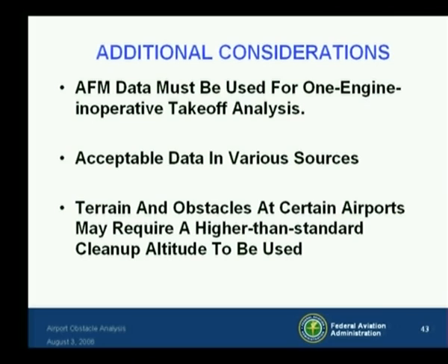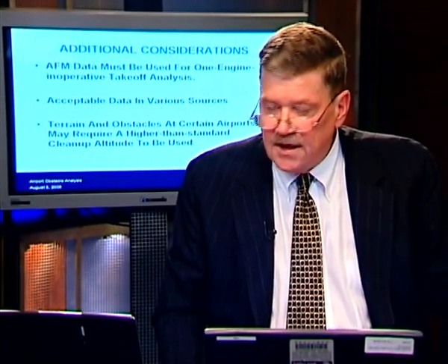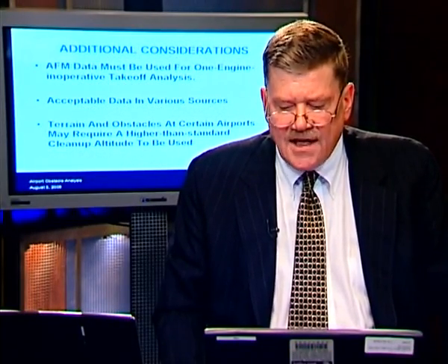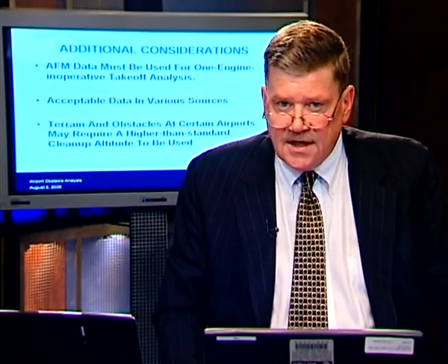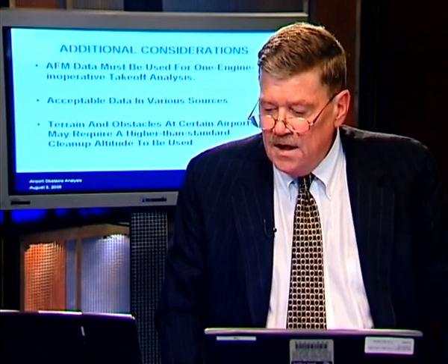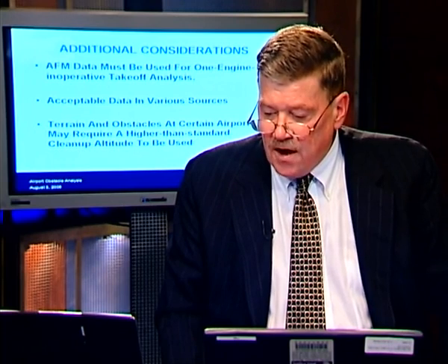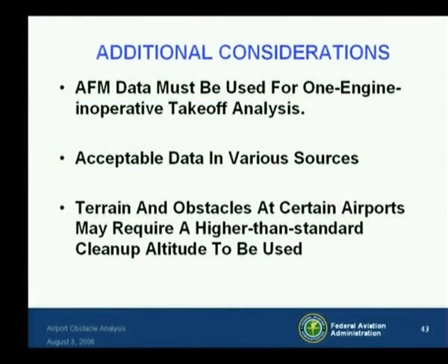Operators may find appropriate acceptable data in various sources, such as, believe it or not, community noise documents, performance engineers' handbooks, flight characteristics manuals, and manufacturers' computer programs, which is probably the most often purchased thing. All the contractors out there usually have performance data for the airplanes in excess of 1,500 feet. The terrain and obstacles at certain airports may require a higher than standard cleanup altitude to be used and may still allow acceleration and cleanup to be accomplished within the takeoff thrust time limit, usually a 5-minute limit.